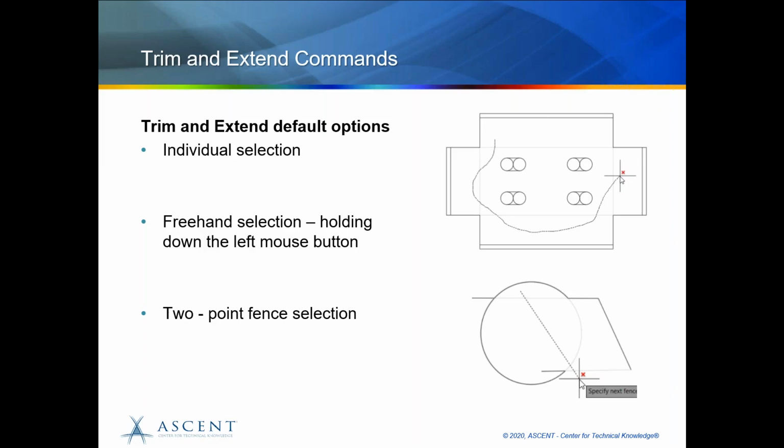So as you can see here on the screen on the right hand side, in this area, you can see these 4 light gray, faded lines. So what has happened is that I started from here and then kept on moving in a freehand, holding the mouse button, and then moved it around here till here, and all the 4 lines could be taken off or trimmed in a single command.